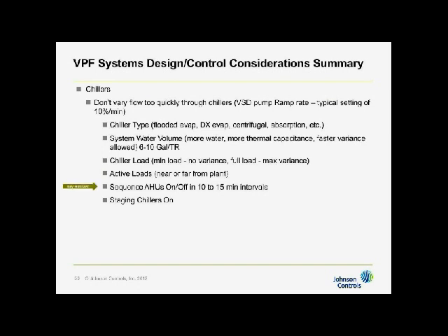Right? There's another thing that has nothing directly to do with the chiller, but remember, with a VPF system, I'm no longer isolated from what happens at the air handling units. When I'm in primary secondary, I'm hydraulically decoupled from what's going out there in the secondary, from flow and head changes as I change valves and so on. But no longer am I. And that means that you don't want to shut a bunch of air units off at once and close their valves, because you'll get a sudden change in flow, and that will trip the chillers off. So sequence the air handlers on and off in 10 to 15-minute intervals, so you don't have that problem. All of the ones we just discussed are during normal operation.